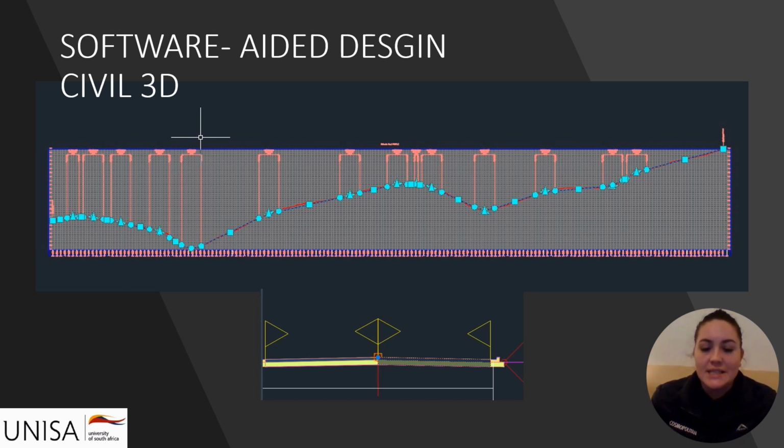I created an assembly. This assembly is the details of the pavement structure. It also shows the drainage, which is a conceptual idea for this project. The slope of the road is also included, which in this case is stated as 2% going left and 2% going right. The next step would be to create the corridor.